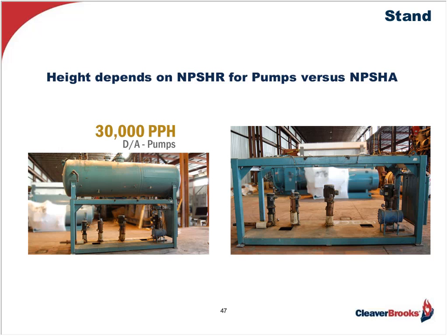To be safe, we normally add about 2 feet, making it 7 feet above the pump's inlet in this case. And by the way, that's what we refer to as NPSHA, net positive suction head available, versus what the pump manufacturer is requiring, NPSHR.